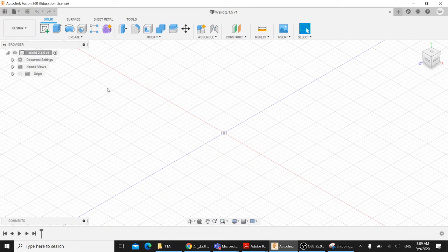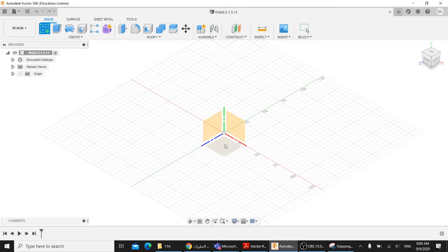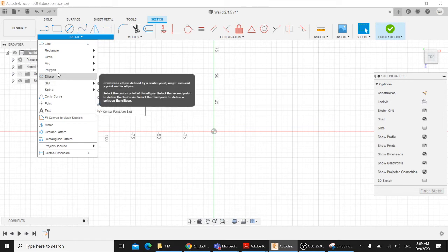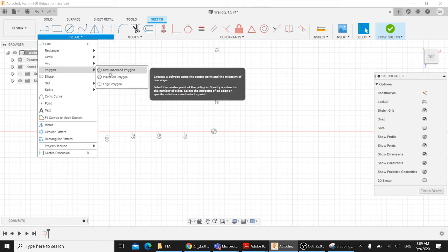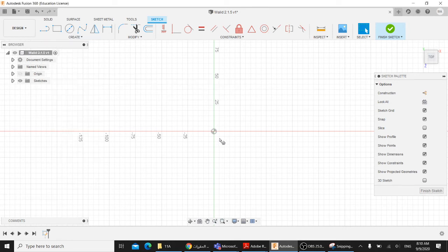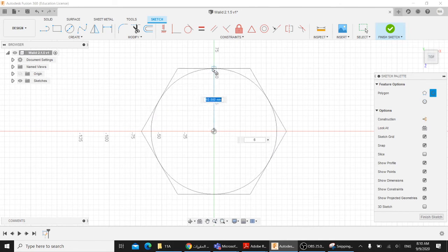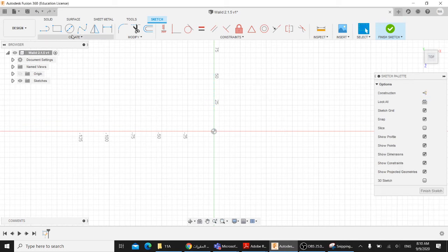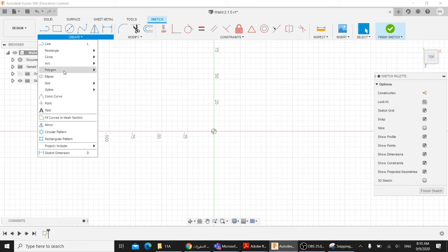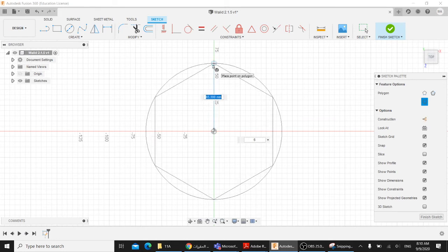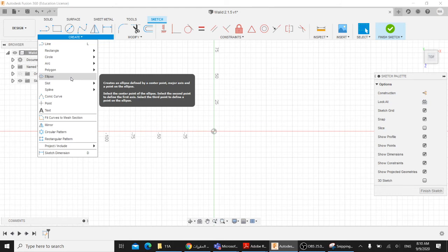So activity 2.1.5 will ask you to create a hexagon. As I told you before, you can create a sketch and create a polygon. Let's make it circumscribed. If you make it like this, it will create a circle inside the shape, just for your help. But if you choose the other option, polygon inscribed, the circle will be outside. See? Let's choose the first option.